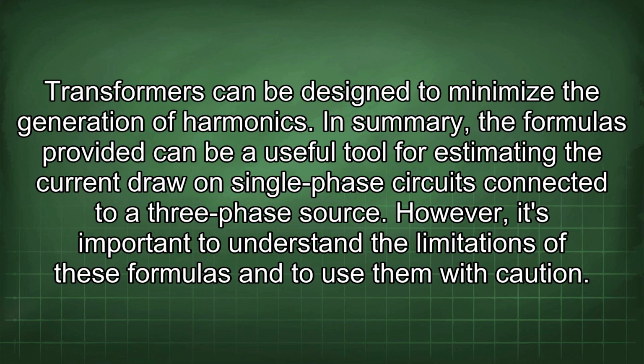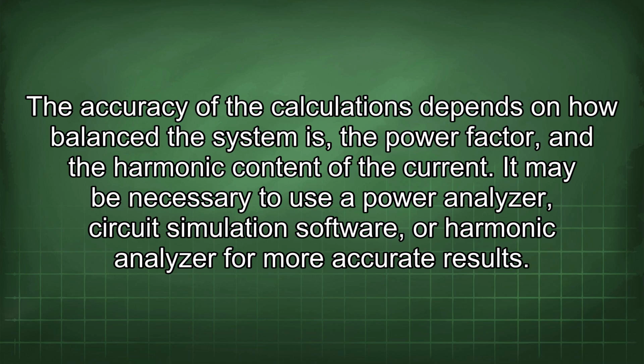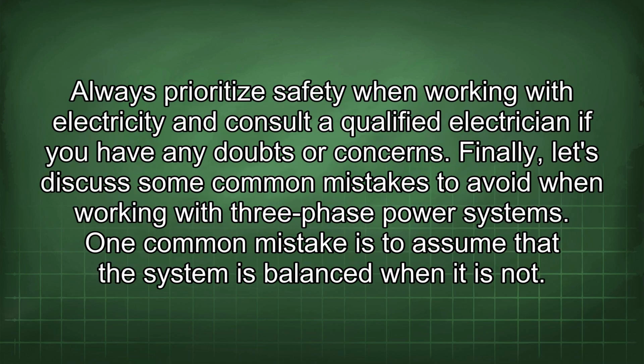In summary, the formulas provided can be a useful tool for estimating the current draw on single-phase circuits connected to a three-phase source. However, it's important to understand the limitations of these formulas and to use them with caution. The accuracy of the calculations depends on how balanced the system is, the power factor, and the harmonic content of the current. It may be necessary to use a power analyzer, circuit simulation software, or a harmonic analyzer for more accurate results. Always prioritize safety when working with electricity and consult a qualified electrician if you have any doubts or concerns.